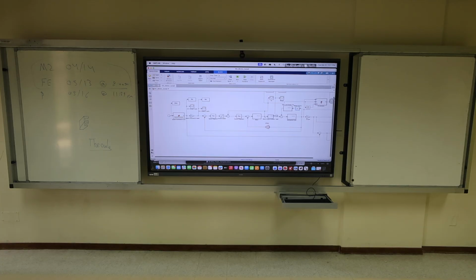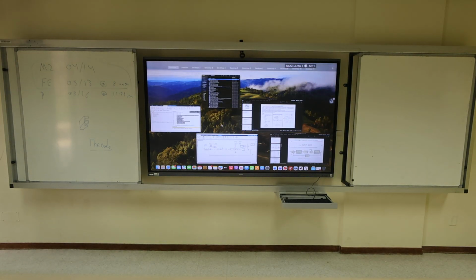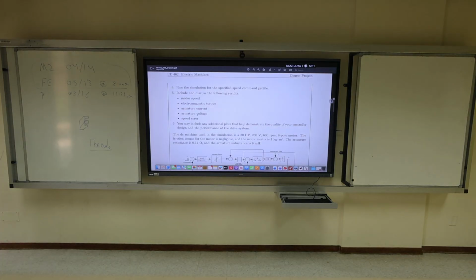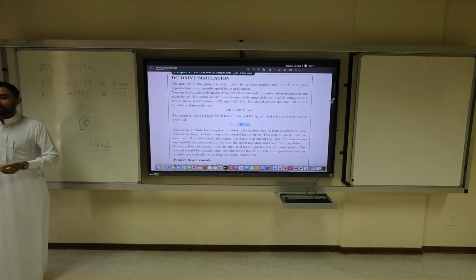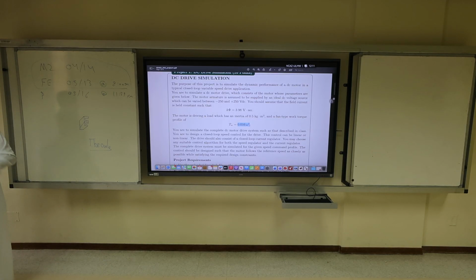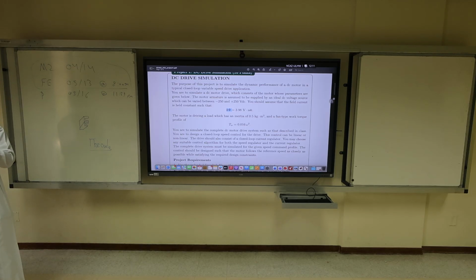What is the model of the speed? It's a fan. So it's a constant, 0.016, times omega squared. You either don't put it as a number, or identify it as a variable. Constant times omega. So this is the K times flux. It is in the unit of voltage times second. Voltage times second times radians per second. It will be what?